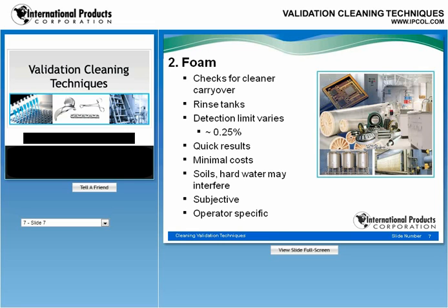Similar to the visual test, the results are very quick, minimal to no cost, just operator evaluation. However, the drawbacks with the foam test are soils and sometimes hard water may interfere with the results. Hard water will certainly reduce the foam, and soils could either reduce or contribute to the foam. And again, it is a subjective test. It is operator specific. So one operator may consider the foam significant and it's time to change the cleaner baths, while another may think differently.